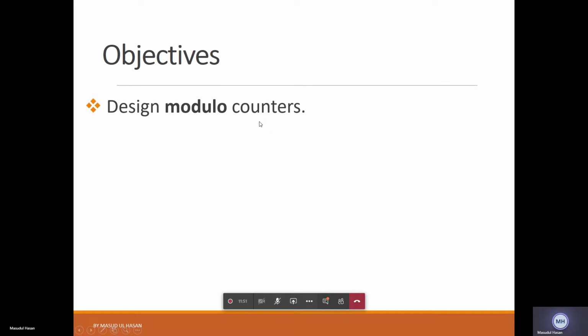Now, this is the same circuit as in the previous slide. If we want to write the code for this one in Verilog, it will be something like this. The module is modulo 10 counter. And these are the three inputs. As you have always seen, these are clock, circuit enable, reset. Here it is clock, reset, CE. And there are 4 output bits, 3:0, and another single-bit output, CEO.